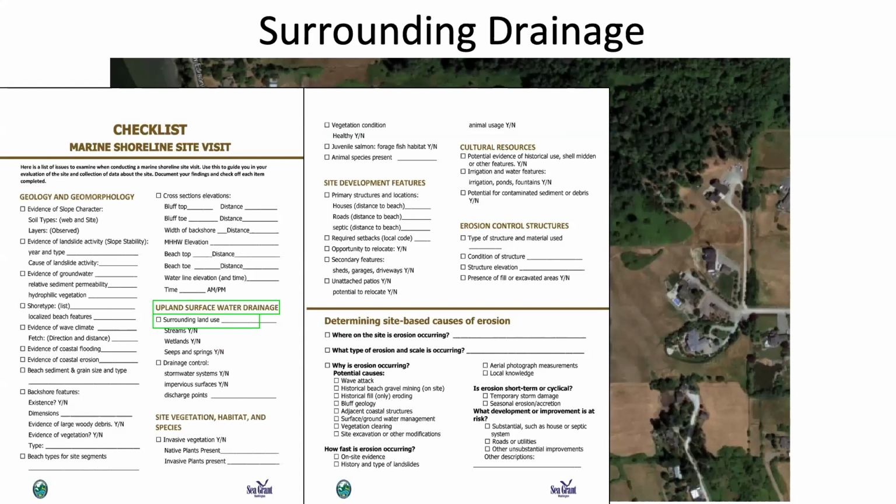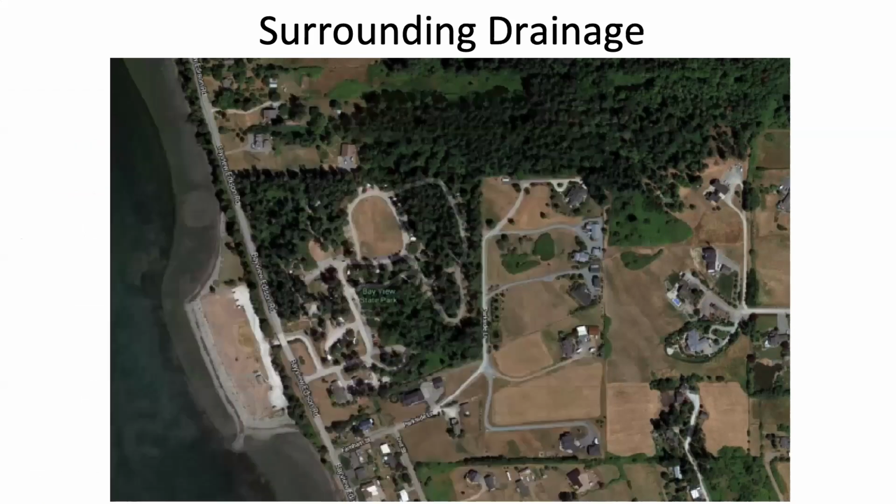Observing the surrounding land is actually pretty simply done. In this case, it's by using aerial photography. Contours, if they're available, happen to be really helpful as well. They help you see what kind of drainage conditions you're dealing with on your site, whether that's urban, which happens to have a lot of impervious surfaces, potentially generating pollutants and more runoff; farmland, which produces less runoff, but will likely come with some extra nutrients, which can bring other issues; or natural, which creates the most favorable conditions for runoff and without pollutants or extra nutrients.